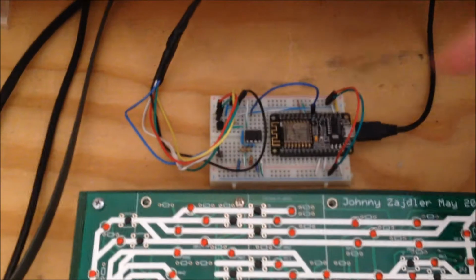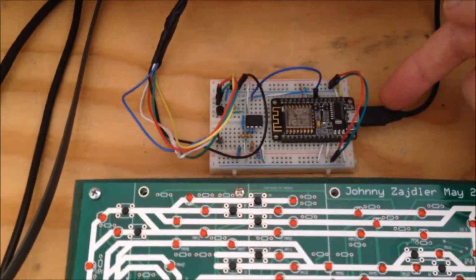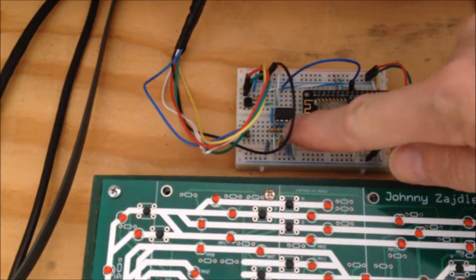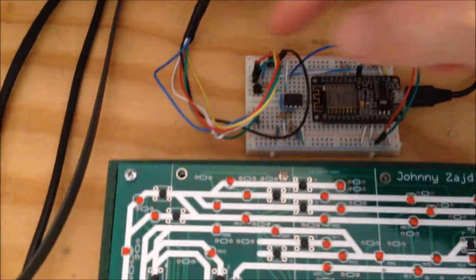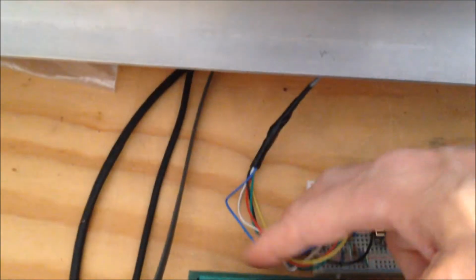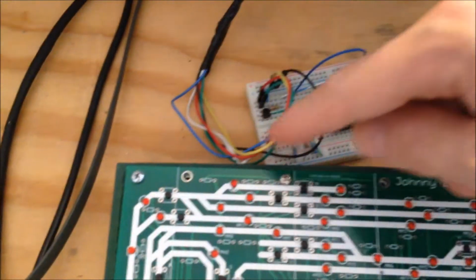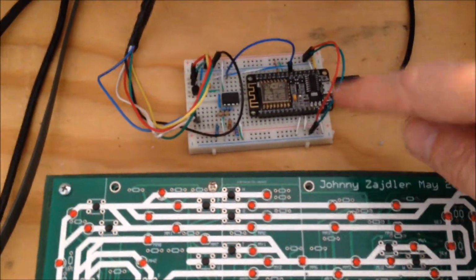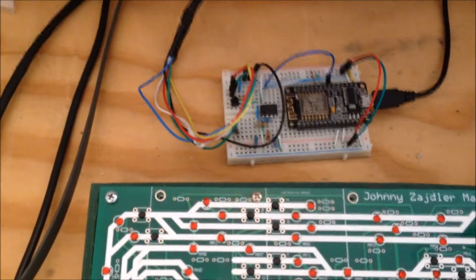The way I have it here, I'm just using this cable for power because it's 3.3 volts, and then I have a little board here, which is what they call a comparator. It listens for signals on the LocoNet, which is this wire. This wire is actually a phone connection type wire. It plugs into the LocoNet, so that LocoNet wire comes here, goes to this little chip, and then that information is transmitted. There's an in and an out, so again bi-directional.